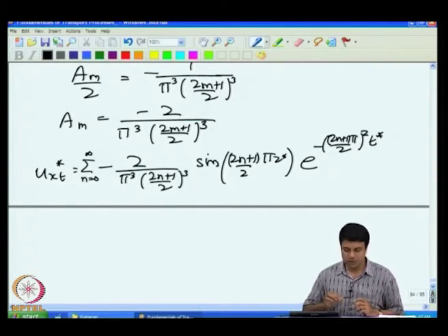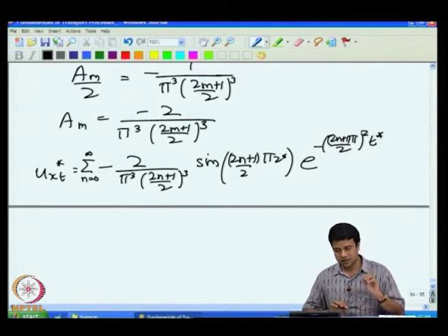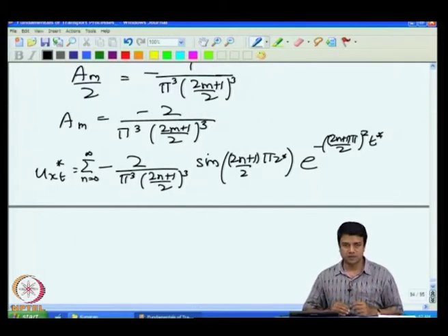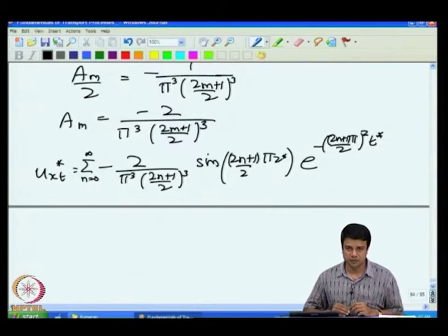So, this gives you a flavor of how one solves the separation of variables for this particular case. When we did the separation of variables for the flow between flat plates, we had to ensure that the velocity on both surfaces for the transient part was 0. In this case, we had to ensure that there was no inhomogeneous term in the equation of motion. So, that is the only difference. This is a second example of separation of variables that I have shown you in order to solve the transient problem. This is an example of momentum transfer where there are sources and sinks.